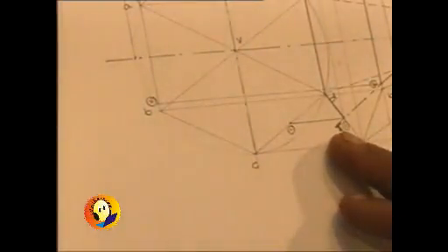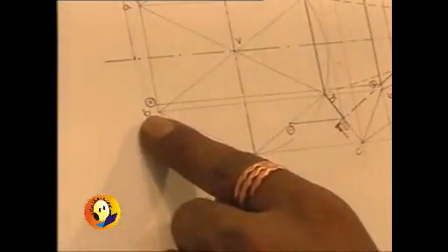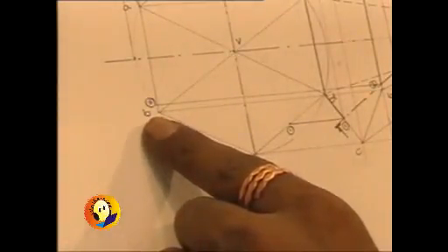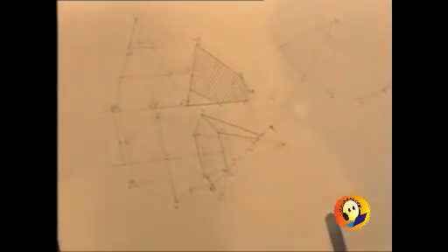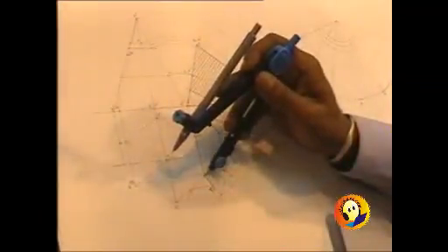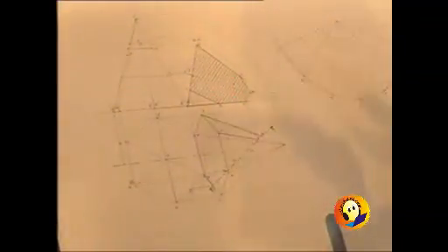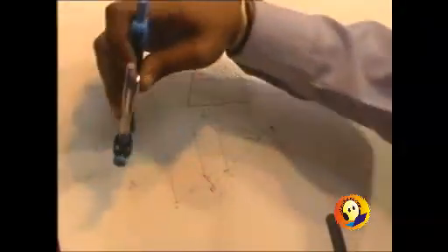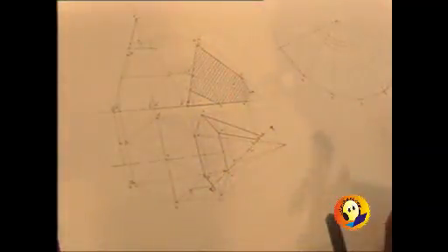These 2 points which we have here, point number 1 and point number 2, which lie on CD and on AB, should be transferred to the development. On the development, we are required to transfer first of all the distances from the top view. So I am taking the distance D1 in the compass, and from D towards C I should be marking it. So I get point 1, and then from A to 2 I am measuring the distance, and I should be marking it from A towards B.